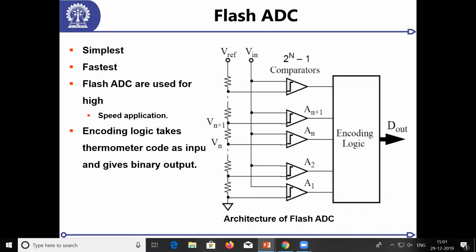Now, how do we make sure that the resistors are all equal? It's very difficult to make sure. I cannot find out whether they're equal or not. We try our best to make them equal, but they might not be equal at all. So our goal is to estimate how much each one is off from the others. That is called figuring out the parameters inside the system. Once we know how much each is off, I get the digital bits and can do some correction on these digital bits to get back the proper ADC output.